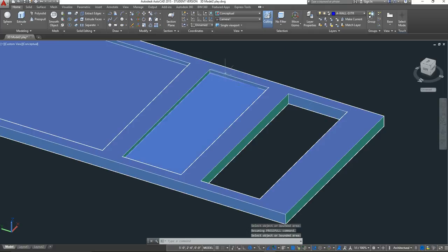and I'm just going to repeat that step again. So I'm going to make sure again I'm in my home tab. I want to go to my coordinate section, make sure that this unnamed reads top. Go get my rectangle tool, take it to the midpoint. Oh, let's make sure that's at top there. Okay, perfect, top. Okay, rectangle.